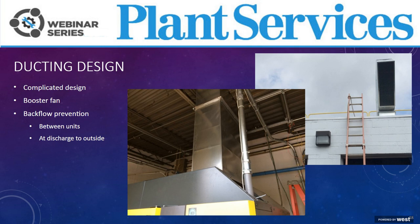As mentioned, the size of the cooling air discharge is not indicative of the necessary duct size, so it has to do with pressure drop. And often it's very far from reality. This particular duct was marginal at best, and so we had some back pressure issues and some overheating issues. Consider the size of the cooler as a baseline point for how big the duct needs to be. Certainly a starter, but not an end-all be-all.